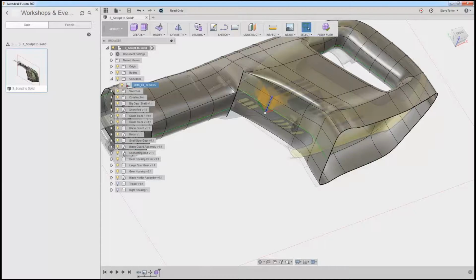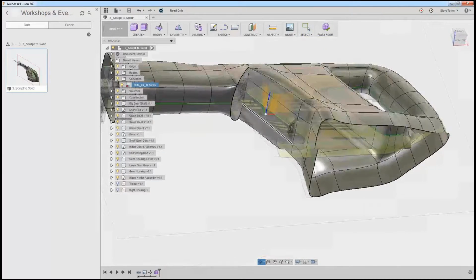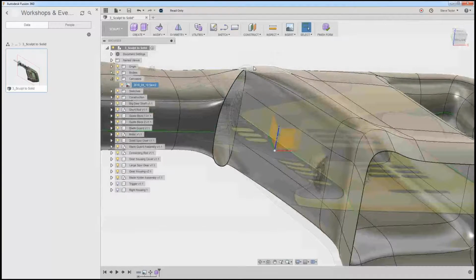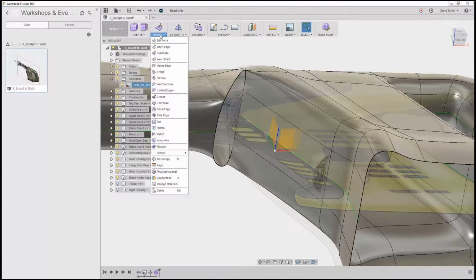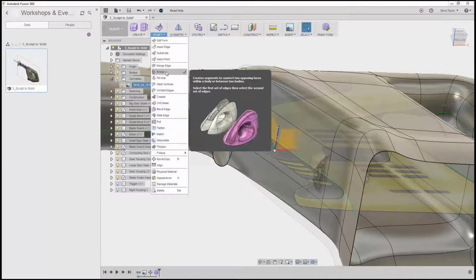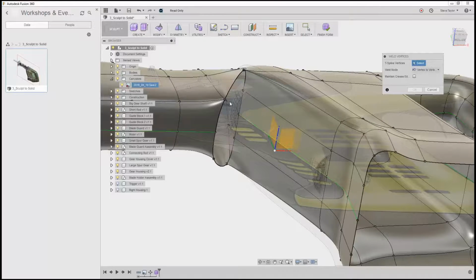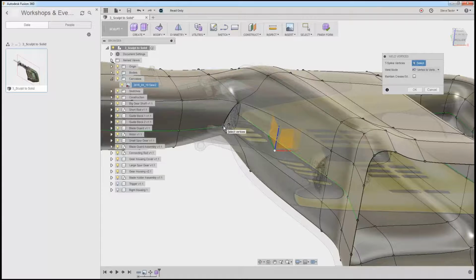So the last step is to actually weld up now these vertices. So I've now got this gap here. You can see there, I've got my center point, so I know that that's going to weld to that. Let's see what we get. So modify. If we now go weld vertices, if I go that one to that, and because the mirror's on, it's done it automatically on the side, and that one to that, and there you go.